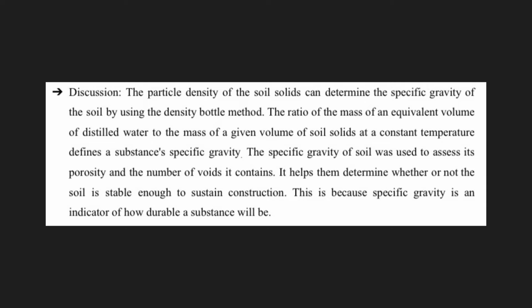The discussion of this experiment is the particle density of the soil solids can determine the specific gravity of the soil by using the density bottle method. The ratio of the mass of a given volume of soil solids to the mass of an equivalent volume of distilled water at a constant temperature defines a substance's specific gravity.